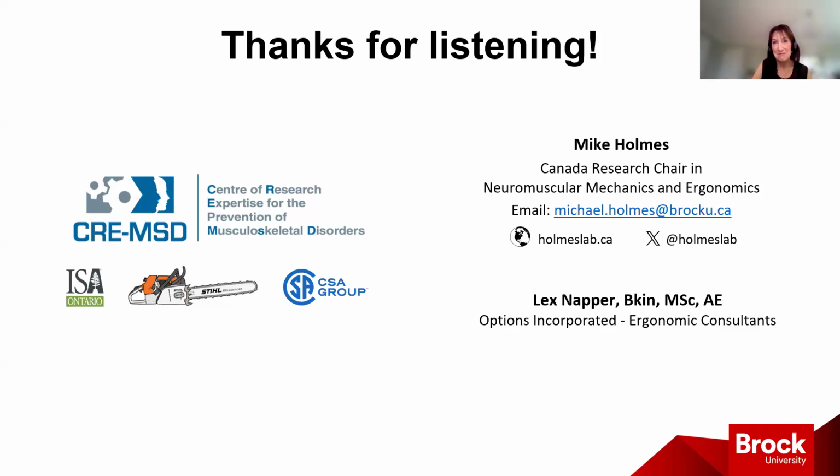I think that's a good answer. I just mentioned on the second to last slide that it's something we're going to be considering moving forward. We acknowledge that electric chainsaws are becoming more and more popular, so we definitely need to test it. We need to explore. We're not really sure what the answers are. Even with our gas powered saws, we really need to capture everything, right? The point of today was to show that the RMS values and magnitudes tell part of the story, but the crest factors and the transmissibility, all of those things tell different parts of the story. So we really need to dive into the electric chainsaws a little bit more.